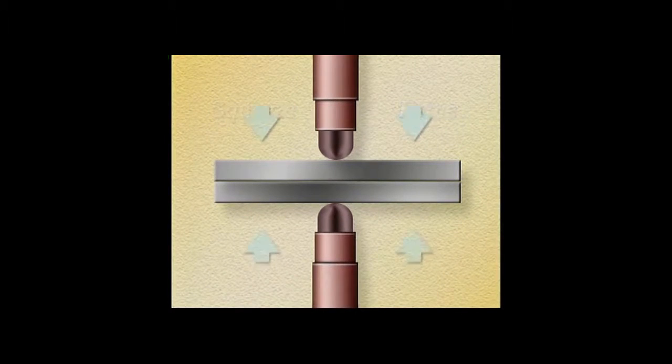Squeeze force in resistance spot welding works differently than you might expect. By increasing the force, you are bringing the surfaces of the parts into closer contact. This reduces the resistance level in the metal stack and causes less weld heat to be produced. In the opposite situation, reducing squeeze force increases the tiny separation between the parts to be welded. This increases resistance and results in more weld heat.